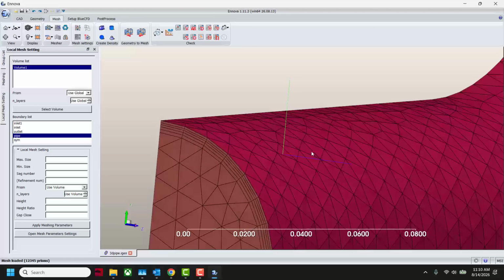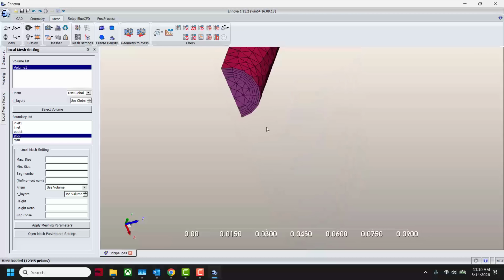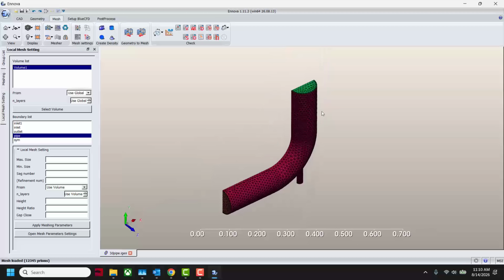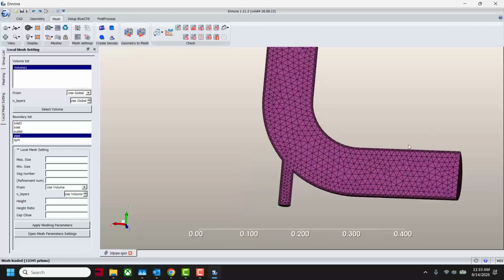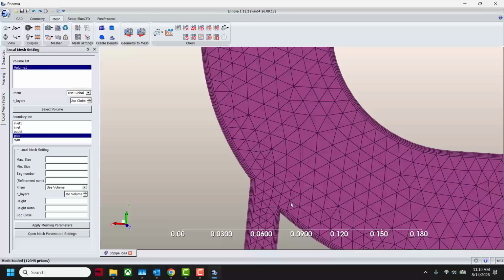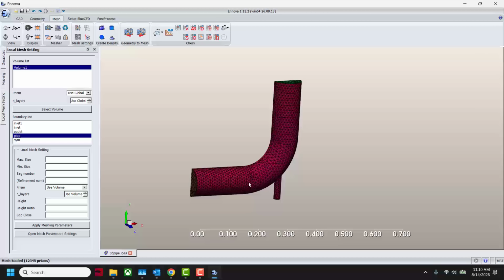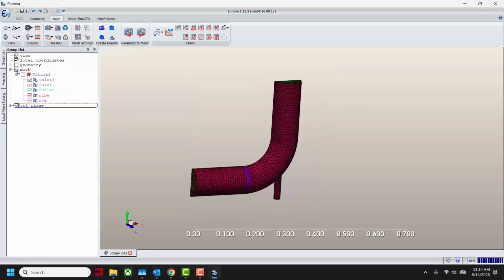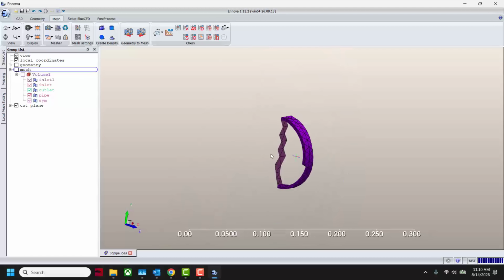And you can see now that they have slid on the inlets and outlets. Let's see inlet again on here. Very, very coarse mesh, just to give you a demonstration. And you can't see any, and slid on the symmetry plane here. So we now have prisms and we now have the surface mesh, but if we do a section through the mesh, you'll see that we don't have anything in the middle. So we have to fill in this middle bit in the volume.